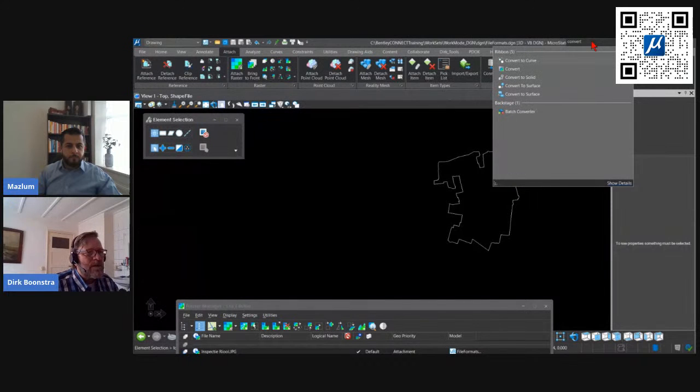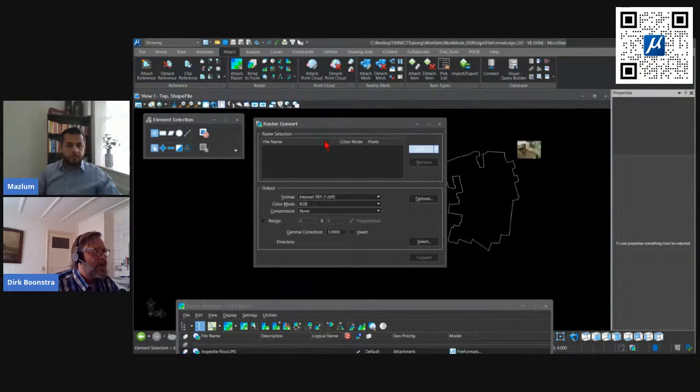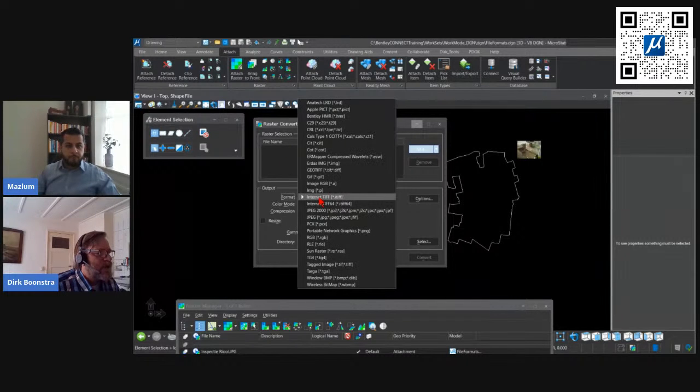I don't know exactly where the command is, so I look over here and I look for convert. It's in drawing utilities, image. There's this dialog where you can do conversions on raster data. A conversion is not the same as manipulating raster data, but if you add a file, you can change your input file to an HMR file, or to RLE, or whatever you want to use. Maybe you have a file without any geographic coordinate system in it, then you could change it over here and go to a GeoTIFF or something like that. So many possibilities.